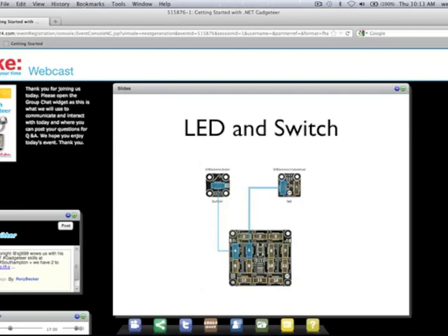If we assume these connections weren't there, and we started to drag a line from the button towards the main board, then on the main board, the sockets that were compatible with that button would turn green, and you could join the button to an appropriate socket. And it simply wouldn't let you join it to one that wasn't compatible with it. So you take this step first, and you, if you like, draw your hardware, and then you go to the real device, and you start plugging the things together as per the diagram, which is a nice way of working.